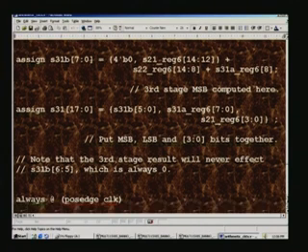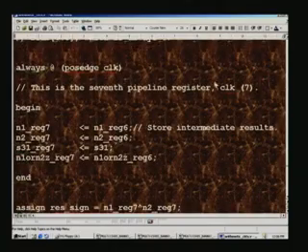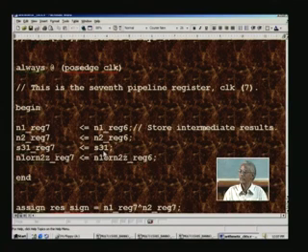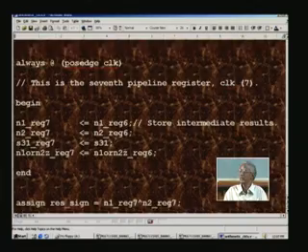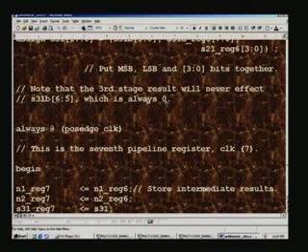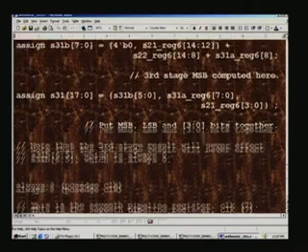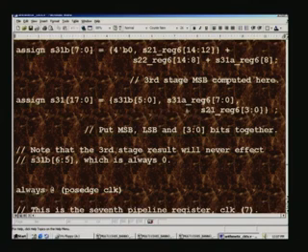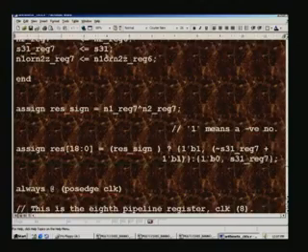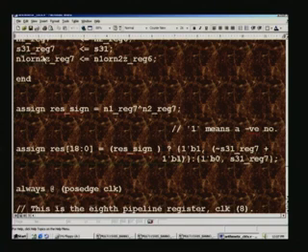And with the arrival of the positive edge of the clock, this is the 7th pipeline register at clock 7, we are once again storing all intermediate results, for example the sign bits, the 0, and also the result from the third stage that we had just computed here. This is the S31 which we had concatenated from the MSB, LSB as well as the unused 4 bits earlier. S31 is the final result there.